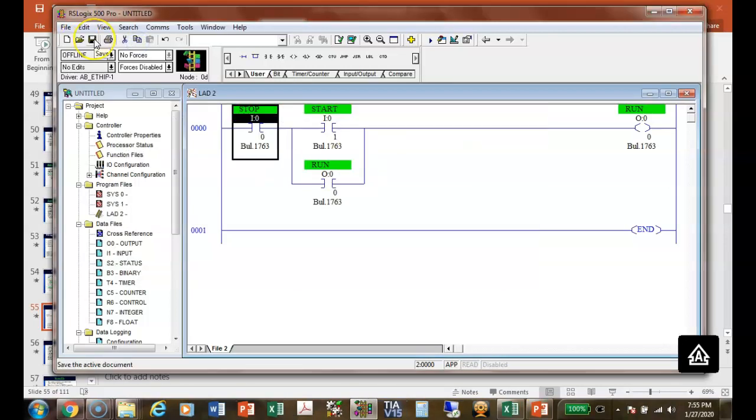Who's active? One, or we can save it right here. Everybody okay? We used to call it the 10-rung rule. So save every 10 rungs because these things are applications, they're computers, and they lock up every once in a while, right? And you've done 50 rungs, and your computer locks up on you, and you do what? Lose everything, yeah, get upset. So we do some that's over 10 rungs in this class, I think, when we get into timers and counters.